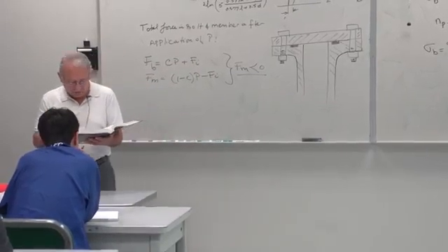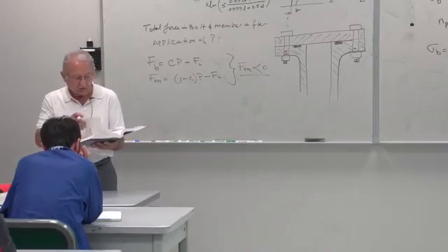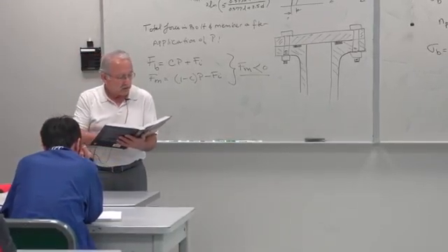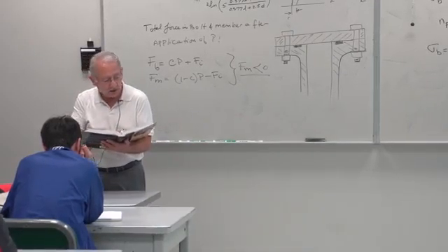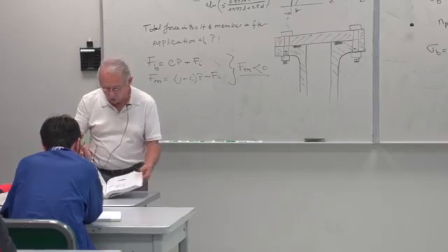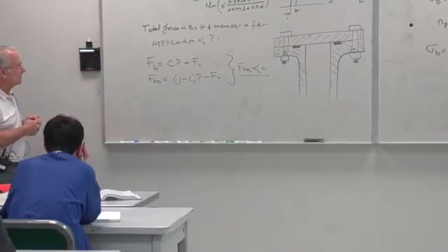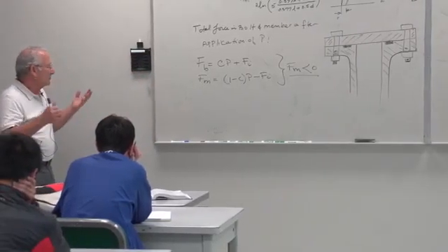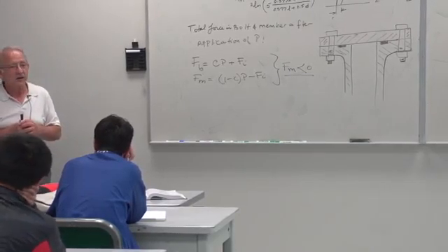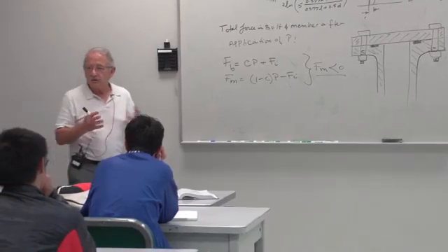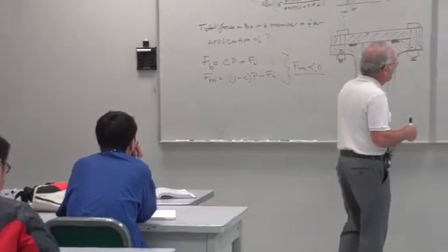For the specifications given in the table for the specific problem assigned, select a suitable bolt length from the preferred sizes in table A17, then determine yield factor of safety NP, load factor of safety NL, and joint separation factor NO. They said to calculate both the yield factor of safety and proof factor of safety. If you have a factor of safety for proof larger than 1, it's certainly larger than that for yield, because the proof load is about 90% of the yield load. But if you want to calculate it, that's fine.